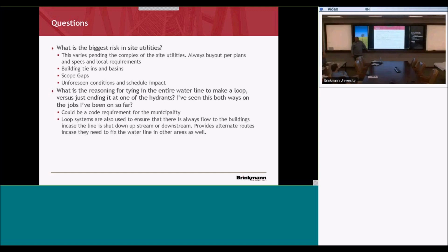So with that being said, if they hit something, they usually end up paying to fix it. What Steve said was private versus public. The public is what is provided by your utility. It's underneath an easement. Its maintenance and responsibility is by that utility provider. Private is when it's off the easement and beyond their gas meter, their water meter, and it's on our site. The owner owns that utility from there on. That's when it becomes private.